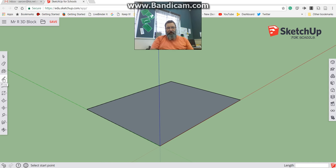And I don't need my line tool anymore. What I want is my tape measure tool. I'll click on my tape measure tool, and I've got lots of options, and I want that top one, tape measure. I come to this corner and I click and I move along that line, and I want to make sure my tape measure is on that line, and then I'm going to type the number 10. I'm not going to click anywhere, I'm just going to type 10 and press enter, and it creates a guide point for me there.